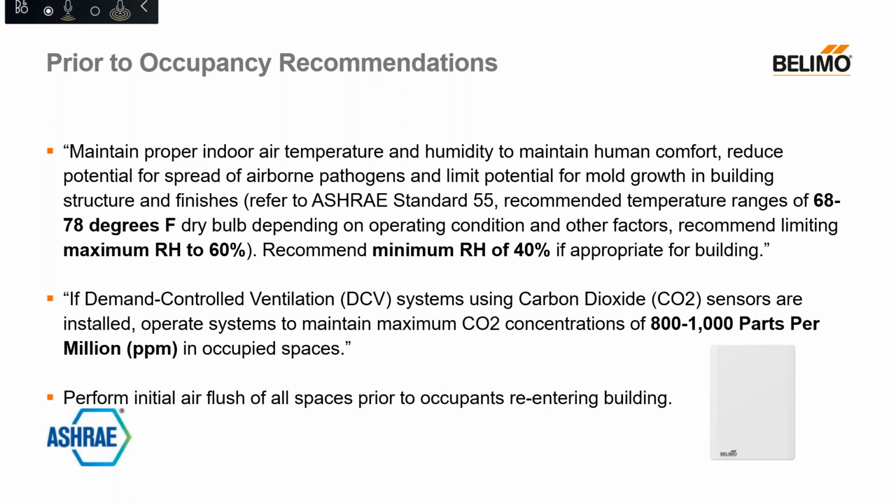Performing an initial air flush of all spaces will be beneficial and cause air change. The goal is to get new air in and old air out, giving a better chance of limiting spread and mold growth.